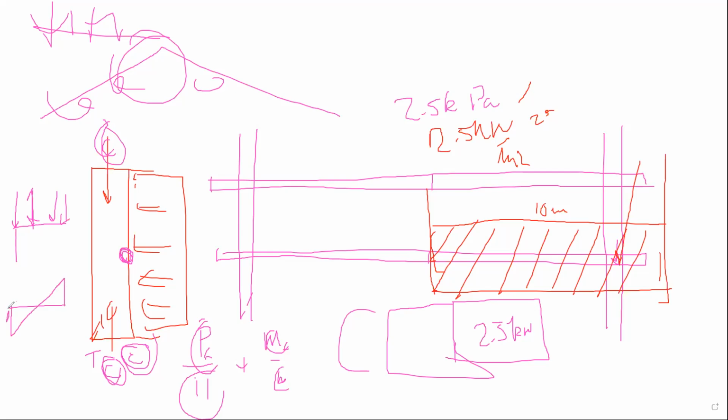So they show the tension here and the compression here, and therefore what you end up with is something like this. The tension here reduces the compression from that force, so it's a little bit smaller, but here they add up, and you want to make sure that the total does not exceed the compression resistance of the member. And that's how you're going to see it in the textbook.